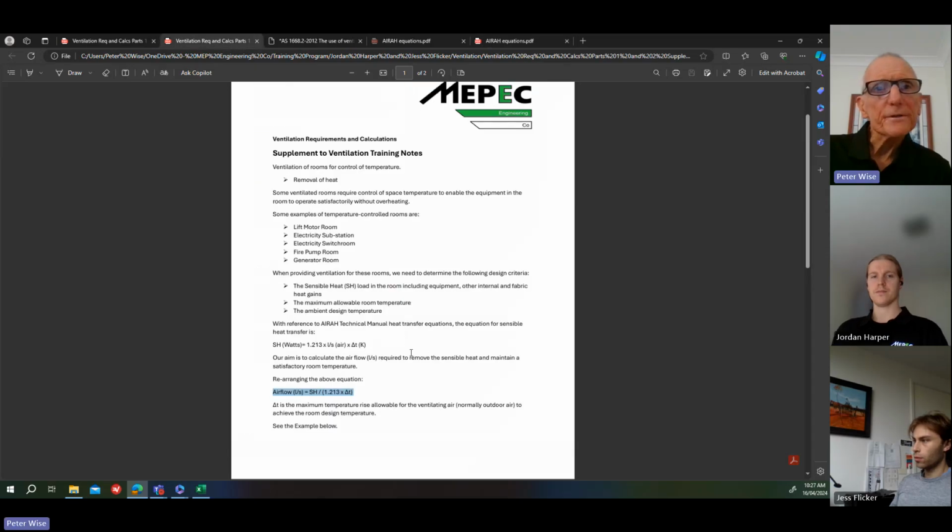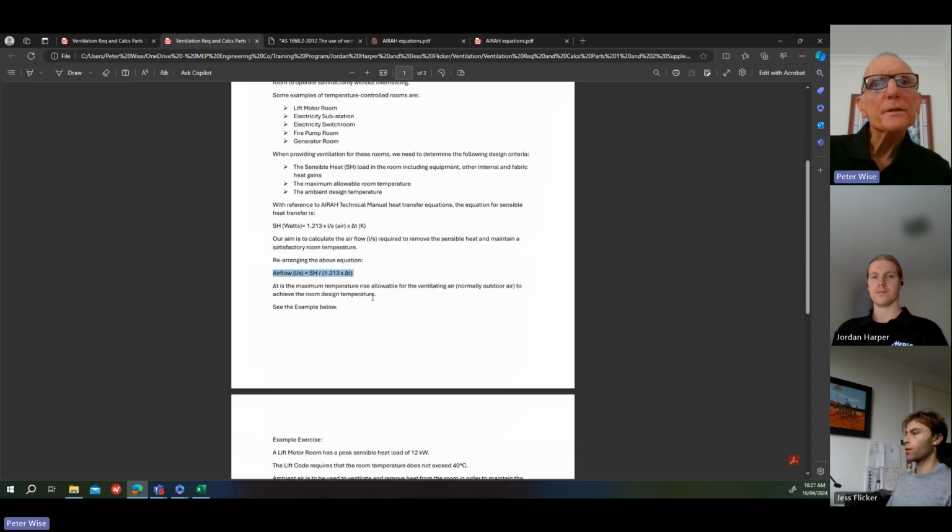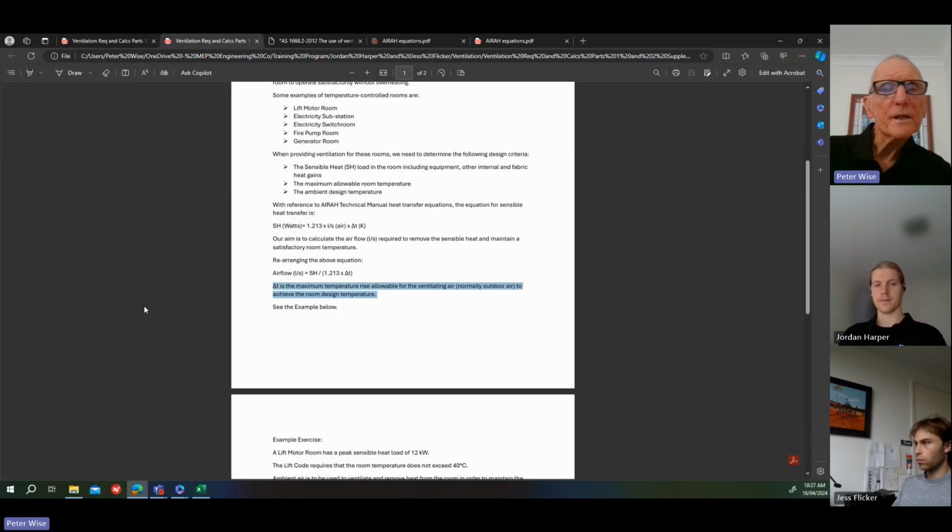So back to our exercise here. Delta T, as I said, is the maximum temperature rise allowable for the ventilating air, which is normally outside air, to achieve the room design temperature. So if it's coming in at 35 and you want to achieve 40 in the room, what's your delta T?